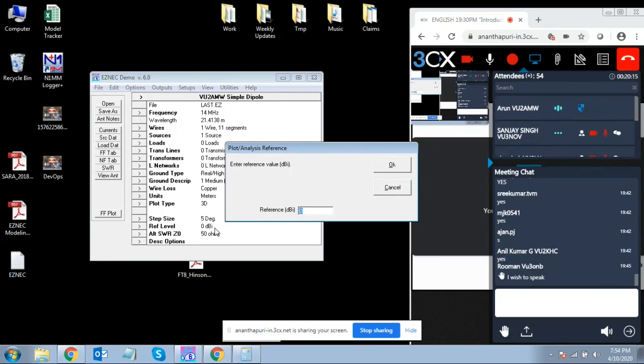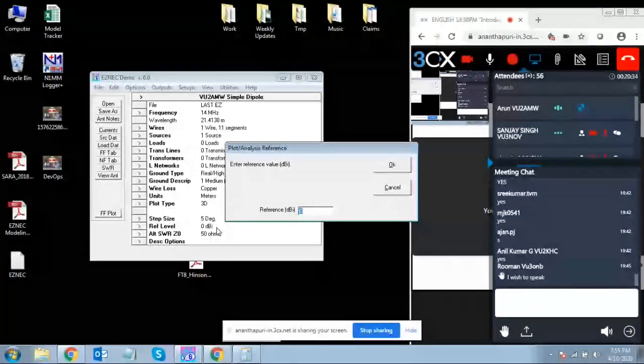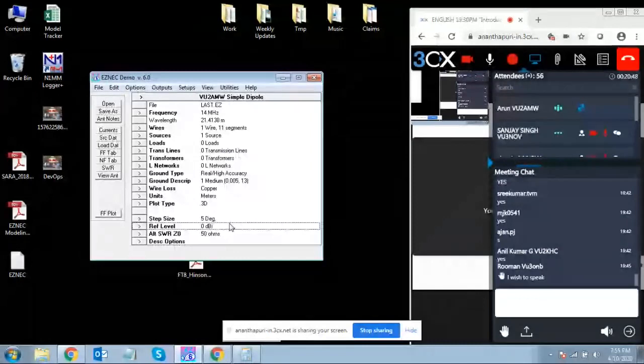It doesn't exist. It's a theoretical antenna. So a standard dipole, I believe it is 2.15 dBi. I may be wrong. So let's compare with dBi. If you want to compare with dBd, maybe advanced options, paid versions of the software may allow you to do that, or you just subtract the gain by 2.15. Since it's a comparison and logarithmic, you can add, subtract, all that. So comparison here is with respect to dBi.